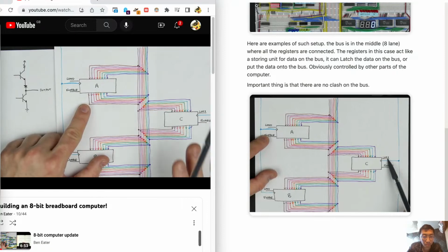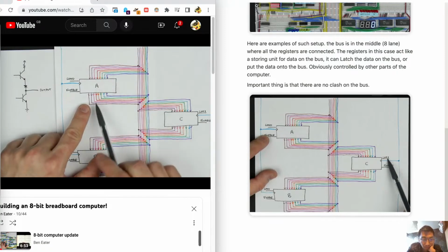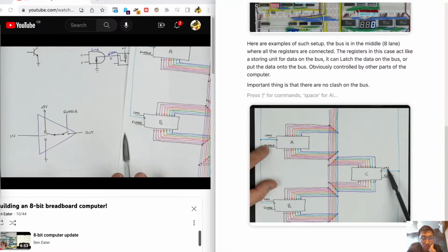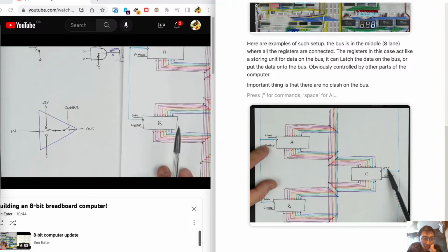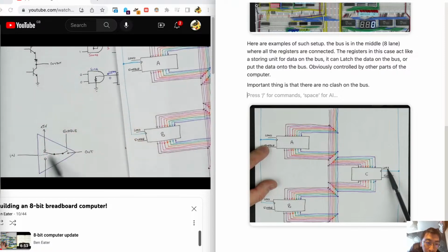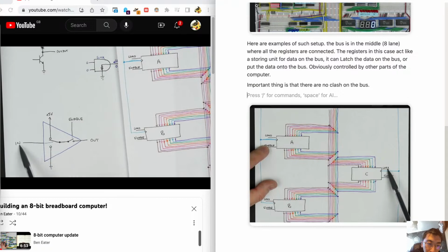And if you didn't understand anything that I just said in terms of sourcing or sinking current, that's okay. A better way, or maybe a simpler way, or a sufficient way to think of this is you can think of a gate in this way. So instead of thinking in terms of what transistors are turning on and off, if you think of it like this, where you have an input coming in, and this is just a simple buffer, whatever the input is, the output's going to be. The input you can think of as just controlling a switch. And so if the input is a 1, then the switch is up in this position and you get 5 volts coming out.